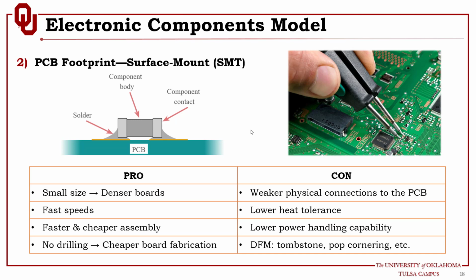Both technologies, through-hole and surface mount, can be used on the same board, with through-hole used for components not suitable for surface mounting, such as a large transformer, for instance, and heatsink power semiconductors as well. When it comes to power electronics, most of these parts are through-hole because they have to handle a huge amount of power, and they will also dissipate a lot of heat. We cannot count on surface mount components for that, and we have to use through-hole components where we have a heatsink